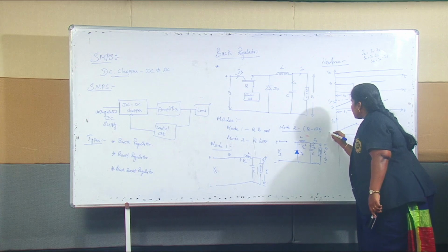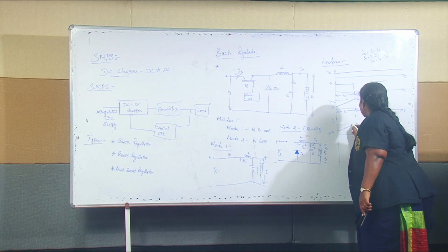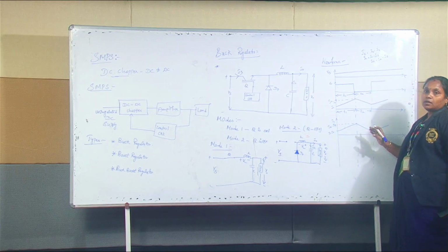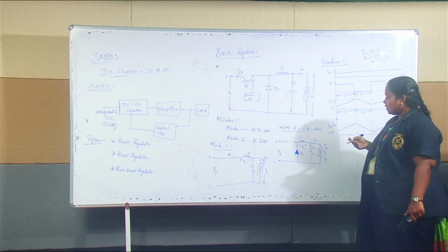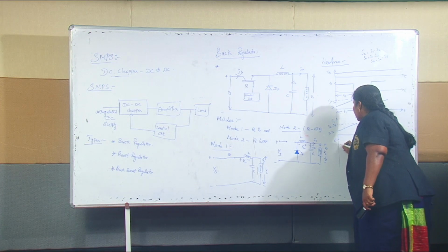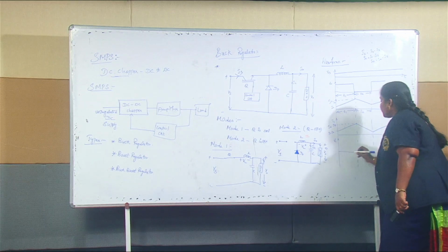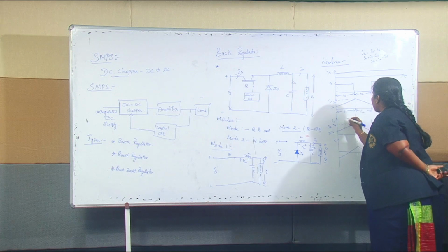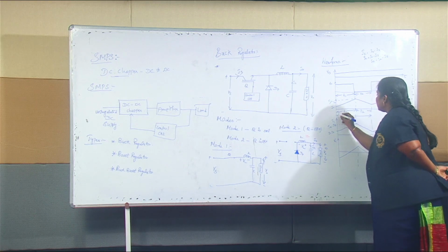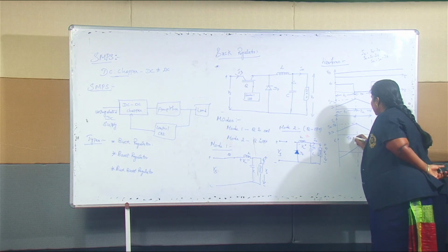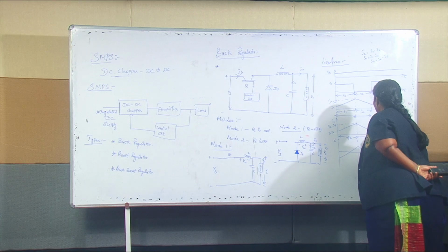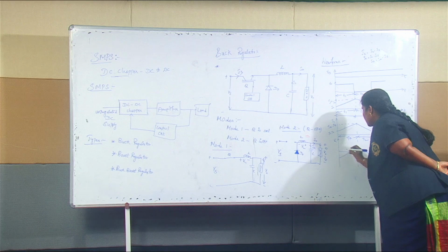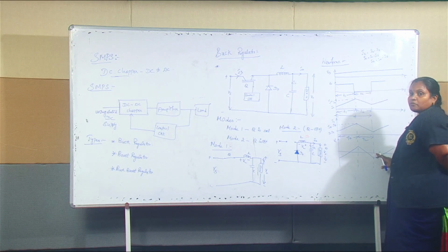So here this value is I1 minus IS, and similarly this peak value of IC is I2 minus IS, right? So this is how you will be getting a current pattern, a current waveform across a capacitor. By taking this one as a reference, we can draw the voltage across a capacitor, right? So this is of a total time period T, and let this one be T by 2, T by 2, and so this is the total time period of the waveform across a capacitor.